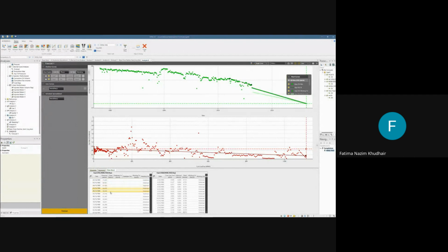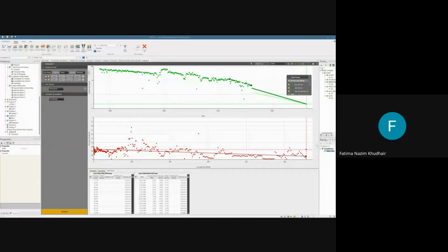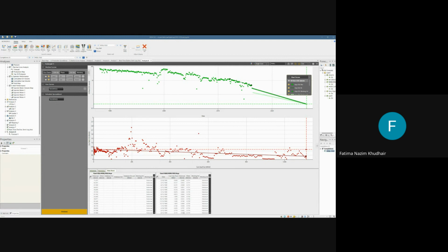And the last thing we have in here is the datasheet. The datasheet will provide you a type of view that is similar to a separate sheet. Okay. And with this one, just right-click and you can export it to Excel. You can export it to Word also. And you can see here this little icon. This is called column chooser. You can pick your columns, which one you want to see, which one you don't want to see. Okay. I will activate it again. I want them all.